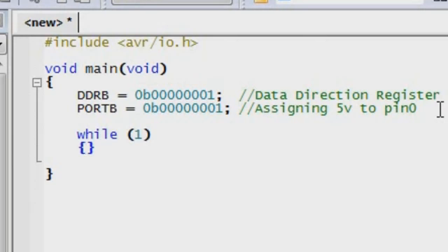It'll also become very clear later on why we do this, and we'll be using this to our advantage. A lot of the things that we're going to be writing will be in this part of the program where we have the infinite loop, but we'll be listening for things to happen, and it'll react to things because the microcontroller will have what is called interrupts, and I'll get into that later. But right now we'll just keep it at the while 1.